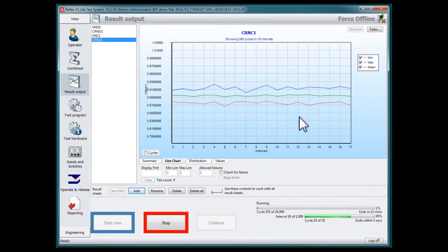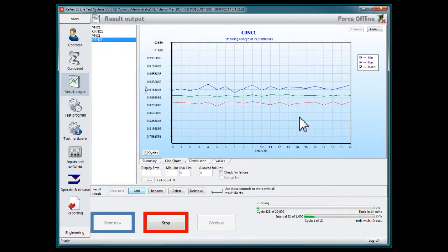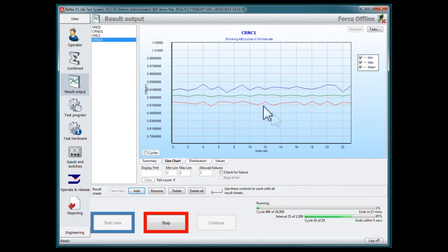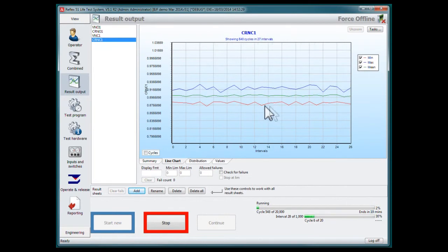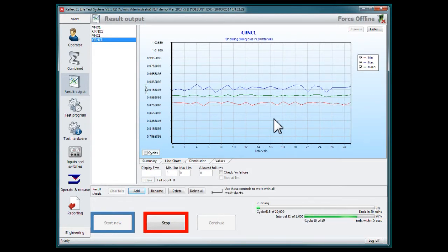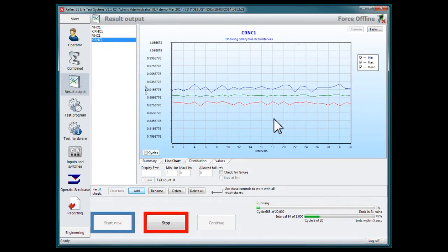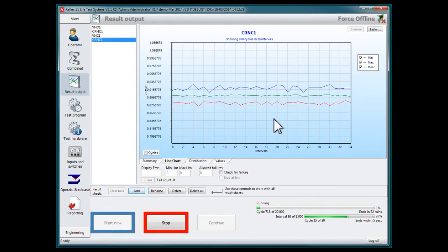This interval testing is useful in two ways. Mainly, it performs very useful data reduction, and in fact we've not lost anything from our data, because you can see that in interval testing mode we've got a maximum, a minimum and a mean line, which allows us to see quite clearly any single cycle that caused some issue wherever it may be in an interval. So we've not lost single cycle testing information.